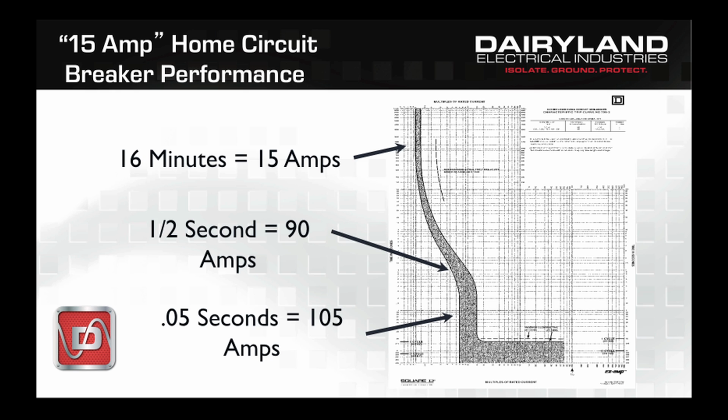So you can see a circuit breaker will pass significantly higher current for short periods of time, but trip at the 15 amp rating only when there is a long duration shorting event. This is an important concept to understand because even though this is a small circuit breaker, the same principles apply to the circuit breakers that are used on large utility overhead power lines.